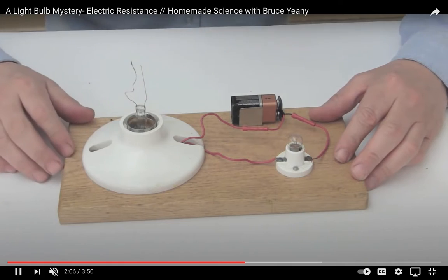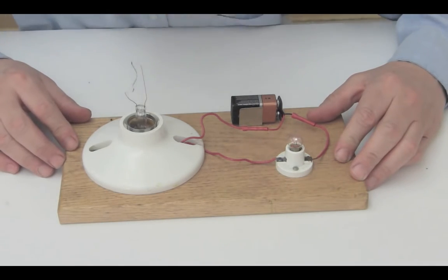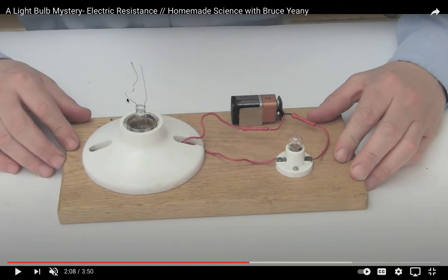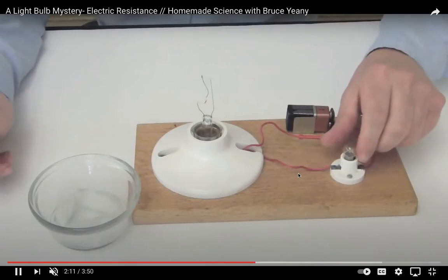What happens is when our guy blows on the filament, he is reducing the temperature around the filament, and hence that's also going to reduce the temperature of the filament as a consequence. And as a result, with the temperature of the filament dropping, the resistance inside the filament drops, which means there's more current able to flow through the circuit, resulting in the light bulb lighting up, as we see right here.